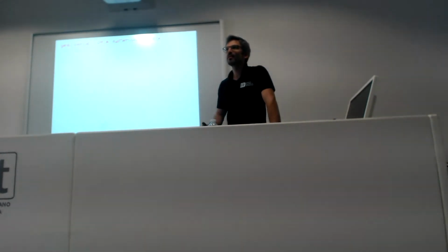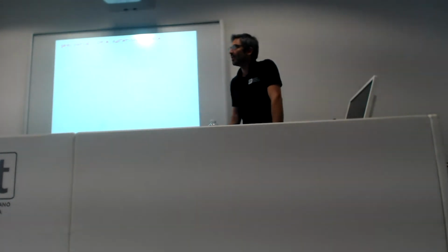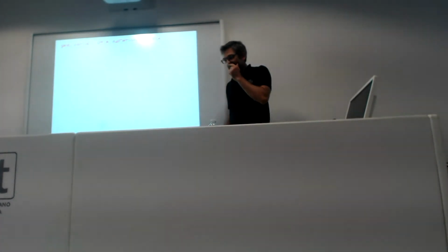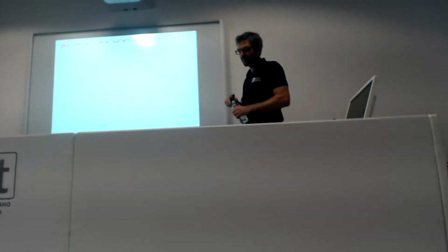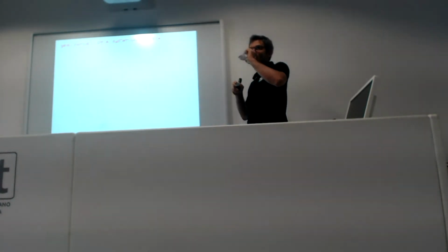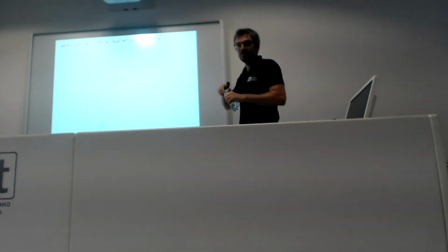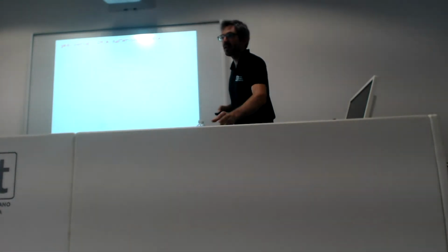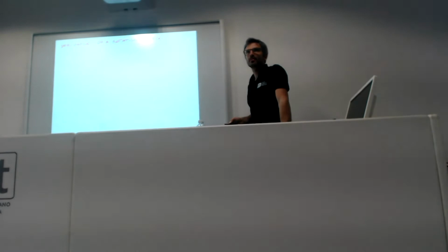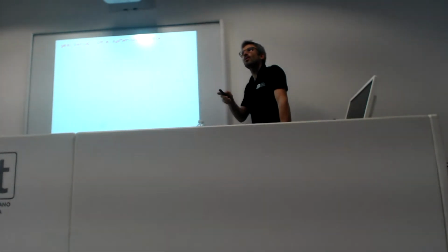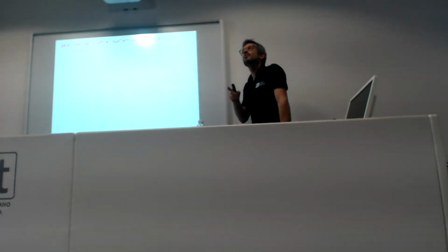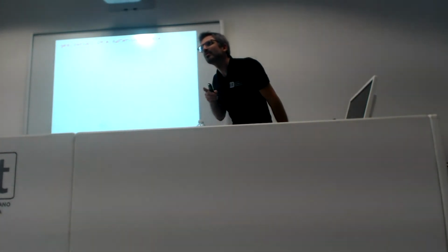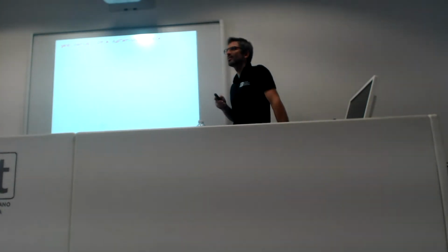Everything is clear? Okay. There is something that we will use in the future that can be useful to define, and it's the derivative of the rotation matrix. Do you know what it looks like? R dot is R times S of omega, the skew symmetric matrix of omega.